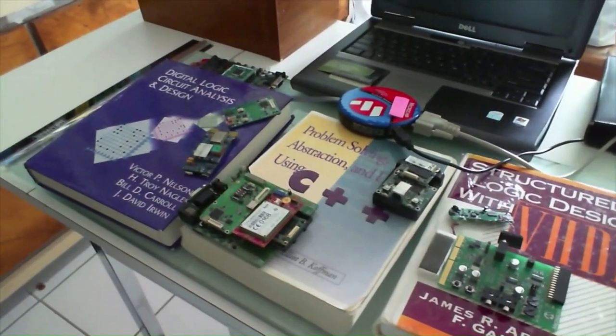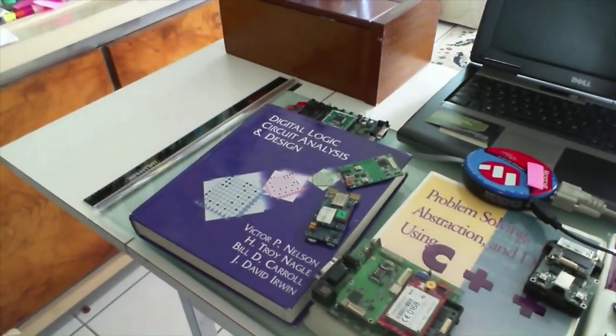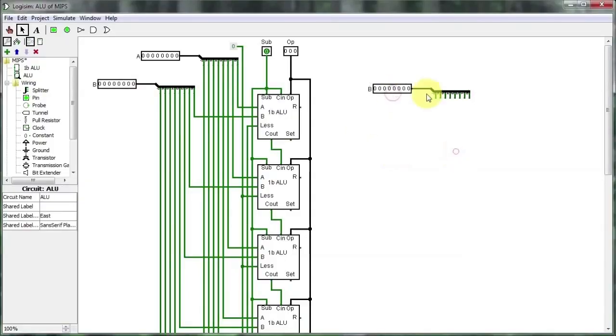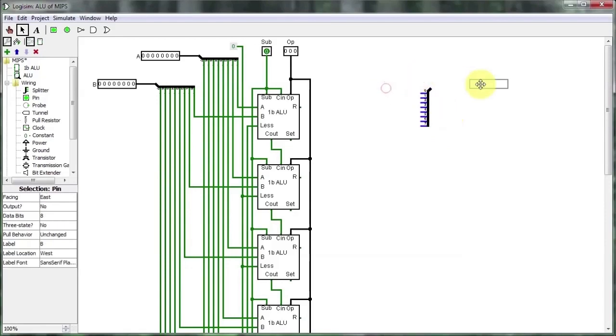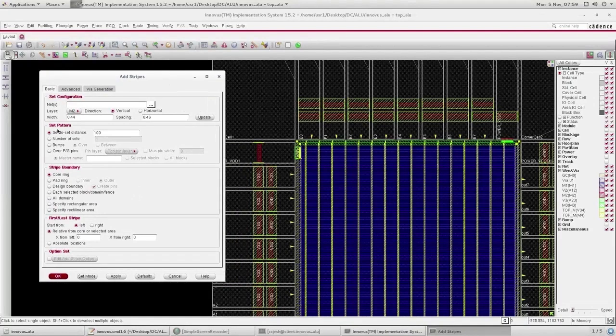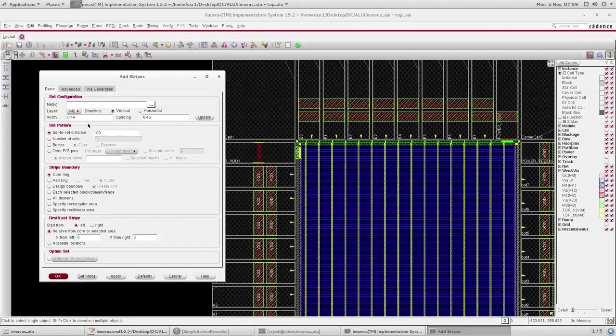So, placement is often run before the logic has been finalized to obtain an early indication of the timing and wireability. At this point, the feedback may be used to influence the logic changes. This may also be the time at which the locations of large objects are determined.